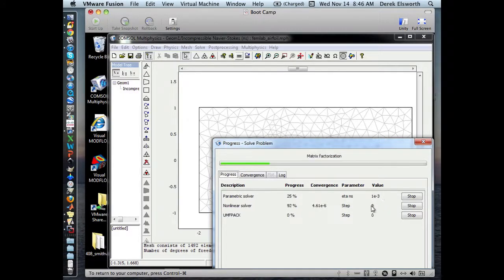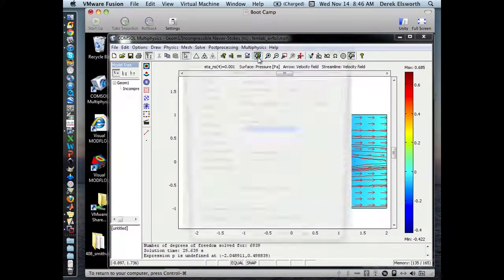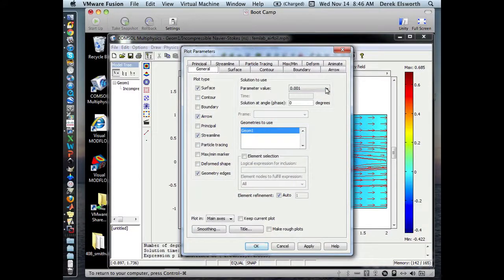As a result of this, it comes up with a flow field, which is shown here. This is the flow field that it solves for. The length of this arrow would be 1 meter a second coming in here. It's 1 meter a second going out. But as it goes around this airfoil, if we go into this, I can do it for different viscosities.